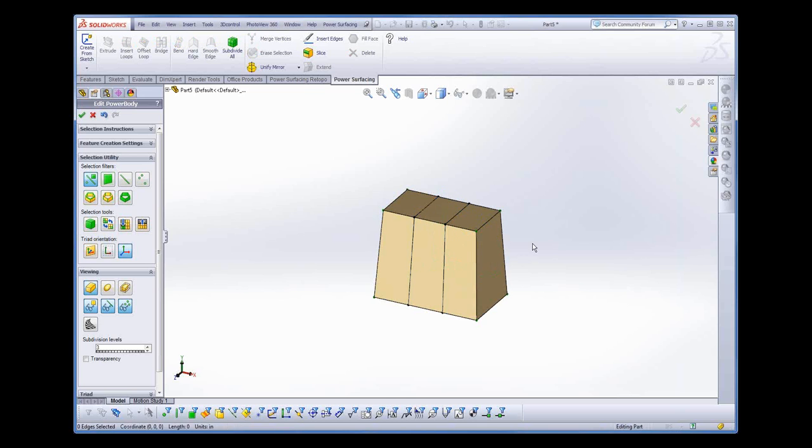So I've set up for my shape here, and now I'm going to select a couple of faces on the top. SubDs, by the way, like to have quads, 4-sided faces. We can get away with 3-sided occasionally and maybe 5-sided, but your result is going to be a lot smoother and nicer if you can keep to quads. Another nice feature is that a lot of our controls can be done with a quick key. If I hold my A key down on my keyboard and hover over the Y direction axis and pull, I can do a quick extrude. It doesn't give me all the options I'd get in the control panel, but sometimes you don't need them. So I've just extruded. I've increased the size here. I'm going to scale them in.